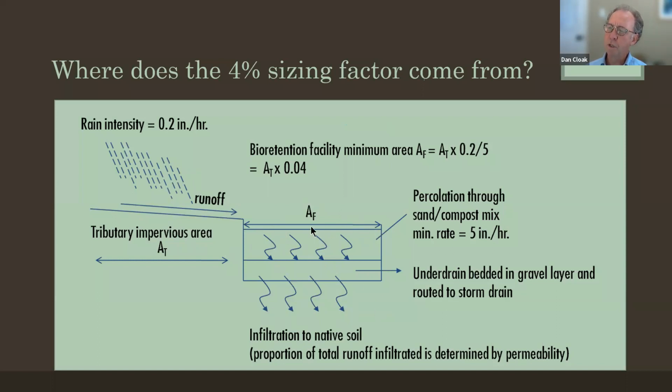And so continuous simulation was used to show that this reservoir has the effect of retaining some runoff and allowing it to be filtered, and therefore this can be smaller essentially. And so that is being used in some very narrow circumstances in some relatively high density development.